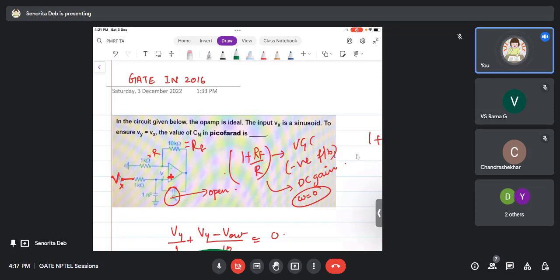Okay, so after a point, it may happen that this circuit no longer behaves as a low pass. So this is basically a low pass filter circuit, you see. This is an R and a C, and the 1 nanofarad capacitor, normally these are used for noise grounding or high pass filtering kind of an action.